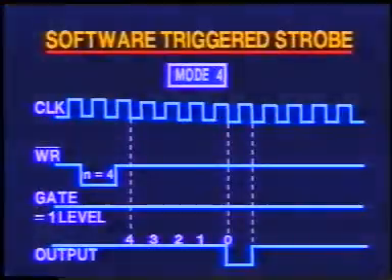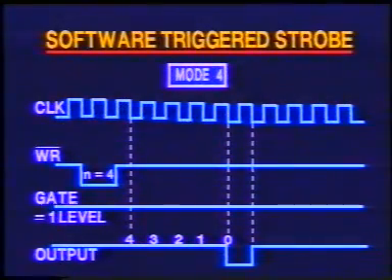When the mode word is loaded, the output goes high. The loading of the count value starts the counting. When the count reaches the count value, output goes low for 1 clock period, then goes high again.